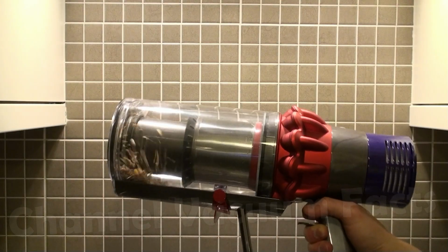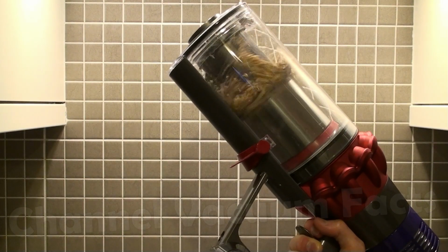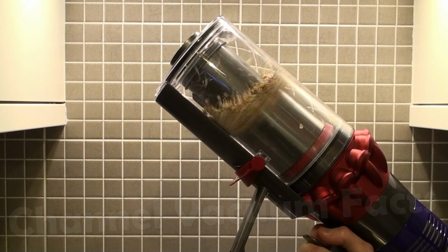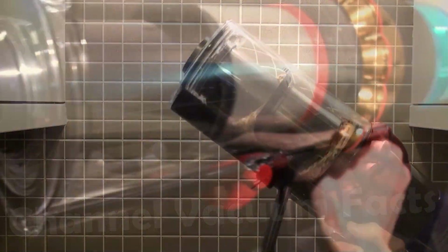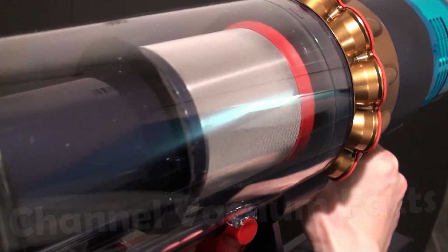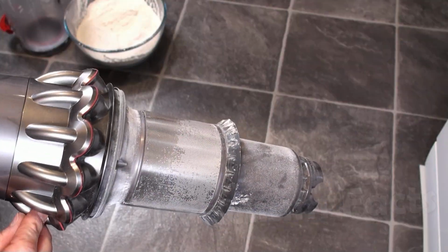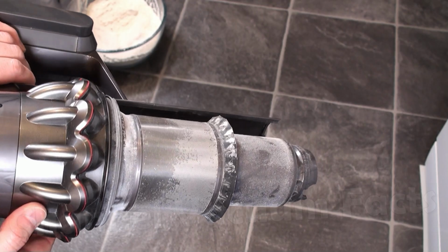This can be semi-separated with a flexible rubber skirt to help retain the dirt at the bottom, particularly when tipped upside down. Smaller particles can escape this relatively weak cyclone and move towards the shroud, which is a mesh of very small holes a fraction of a millimetre in size. The smallest particles pass through and are handled by the smaller cyclones discussed earlier, but larger particles can aggregate on the edges of the holes.